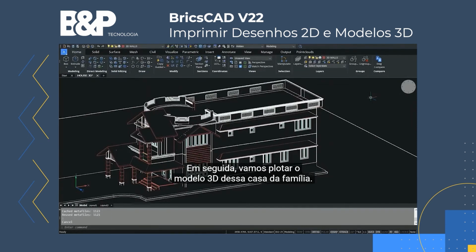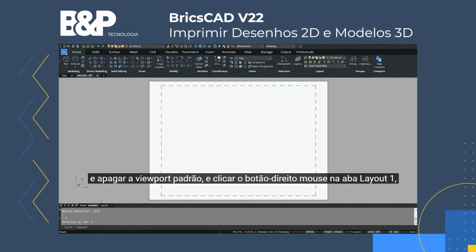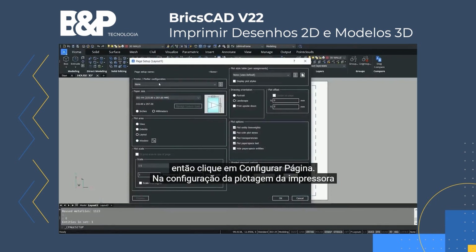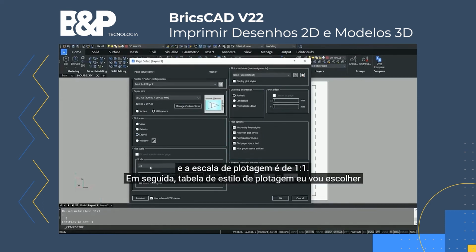Next we will plot the 3D model of this family house. I'll plot a layout. So I'll click on layout 1, then erase the default viewport, then right click on the layout 1 tab, then click on page setup. At the printer plotter configuration, I'll choose print as PDF, plot area is the layout, and plot scale is 1:1.